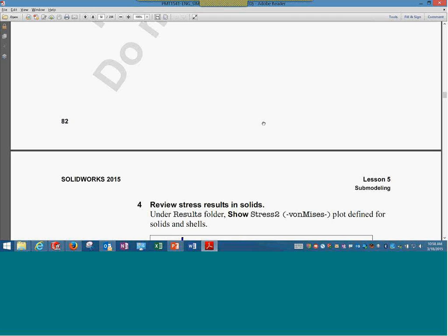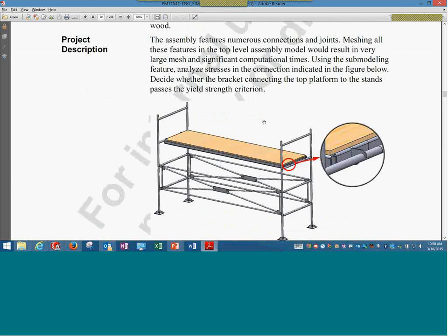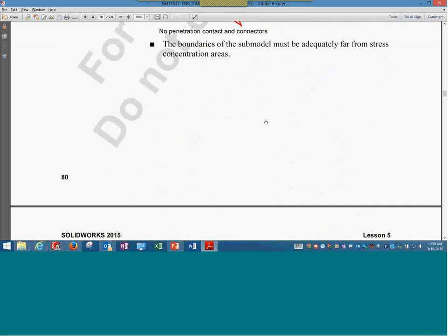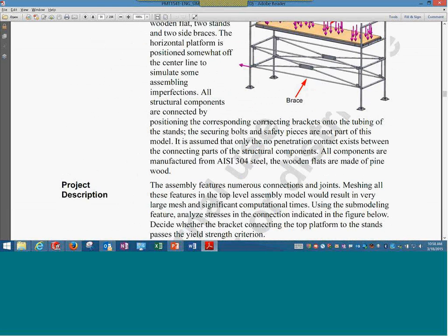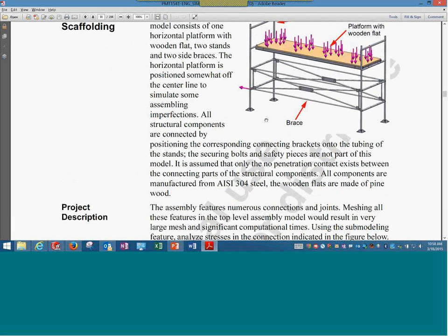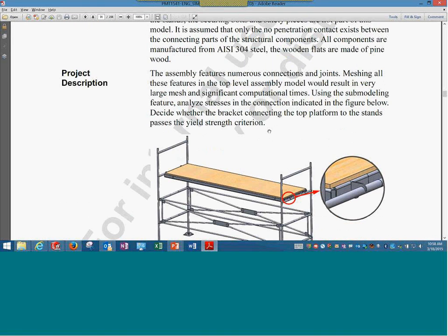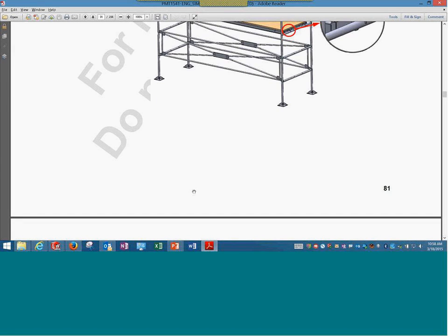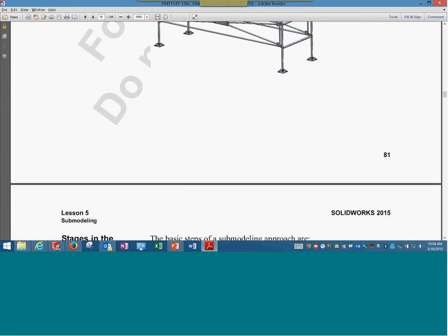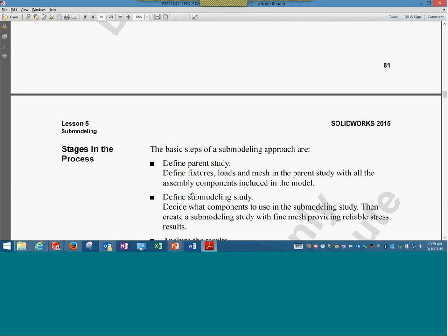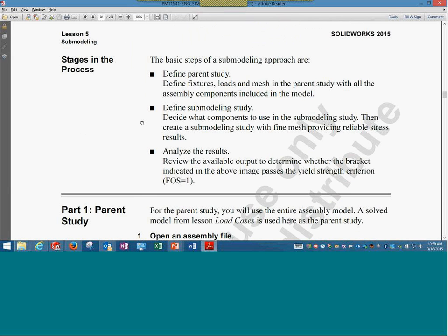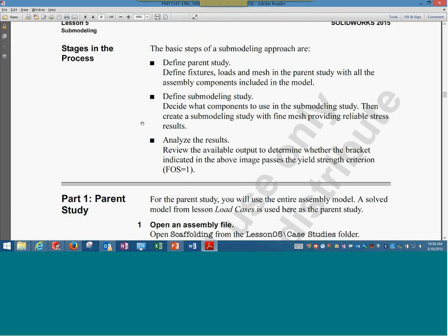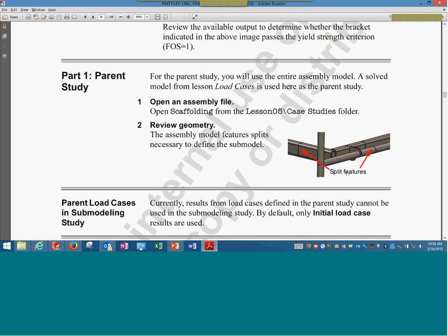Okay. The load case manager as well, we are using the same example. Tip for a load case manager, we need to disassociate the small part which is connected through a contact set. So it cannot be a part of a body, but it is actually at the contact set, because that is the place where it can transfer the load. Analysis can be done. So the small features somewhere around the part are the ones where we need detailed analysis.